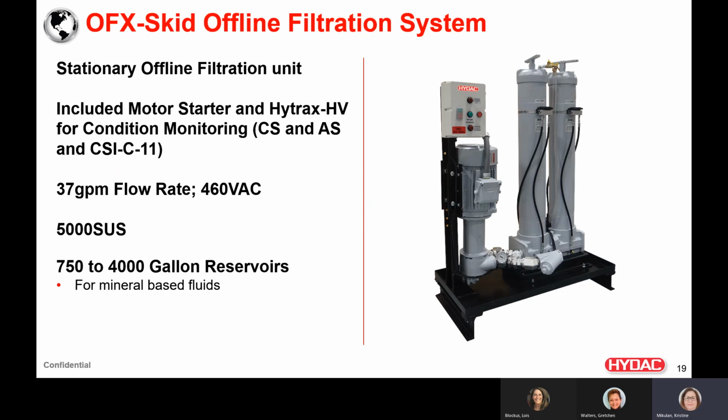Our OFX skid is a fixed flow rate of 37 gallons per minute with our 460 volt, 60 hertz, 3-phase power requirement. It is designed for oils up to 5,000 SUS and hydraulic reservoirs up to 4,000 gallons.